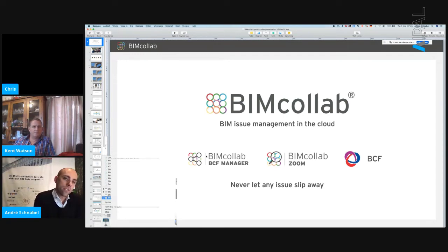To give a short introduction, I'll be showing BIMcollab, a cloud service, together with BIMcollab Zoom, a Revit workflow, connecting it to Dropbox and BIM 360. So having all this as a communication workflow, we use the BCF format. To add to Chris's introduction to that format, the BCF format is a task to other software. It's a small file where the format tells Revit to place a Revit camera in a given location and show some elements that are stored in the BCF file.